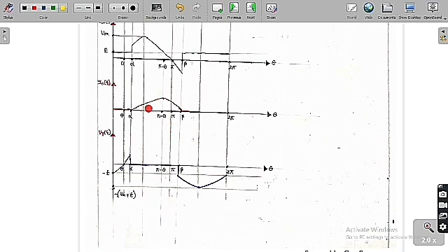A current in an inductor cannot change instantaneously. So it will be charging and then discharging because of the negative supply voltage. So it will be discharging. Because of this only, for the extra region, the source voltage is equal to the load voltage from alpha to beta. Now we can get the output voltage expression, the output voltage average value and the output voltage RMS value. By using that formula, we can figure out I0 average and I0 RMS also. We know the value of TC and the value of peak inverse voltage. All these things we can easily get from these diagrams.